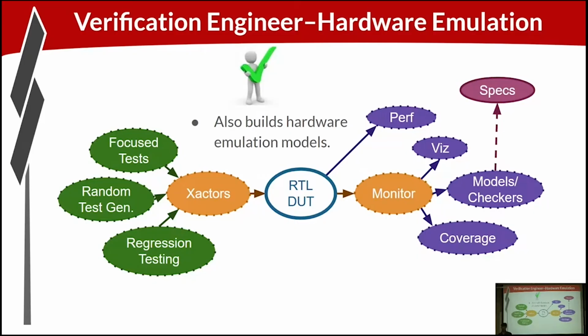Basically, you're running your design in the FPGA instead of running it in simulation. So the RTL DUT, design under test, is synthesizable and therefore can be run on the FPGA hardware. The rest of these components may or may not be synthesizable, and if they're not synthesizable, they need to be run in software on a host platform.